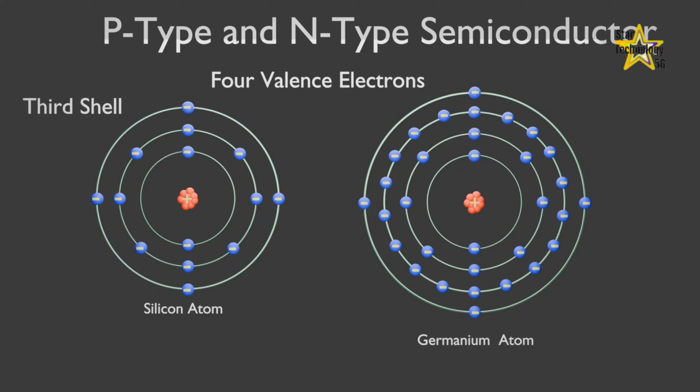The valence electrons in silicon are in the 3rd shell closer to the nucleus, and in germanium are in the 4th shell. This means that the germanium valence electrons are at higher energy levels. Therefore, they require a smaller amount of additional energy to escape from the atom. This property makes germanium more unstable at high temperatures and results in excessive reverse current. This is why silicon is a more widely used semiconductive material.